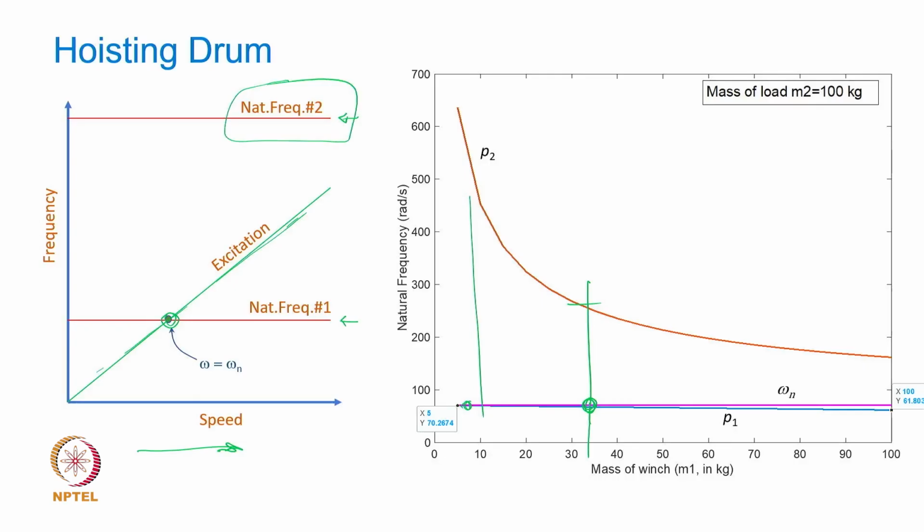So your prediction based on a simplistic model is going to give you a reasonable estimate of the relevant natural frequency, and also of your response as well. Because if you remain within this range of the first natural frequency, the contribution from the second mode to your response is going to be negligible. It will not affect your response. Okay. So when you do the modeling, now we are coming to our first step of the vibration analysis.